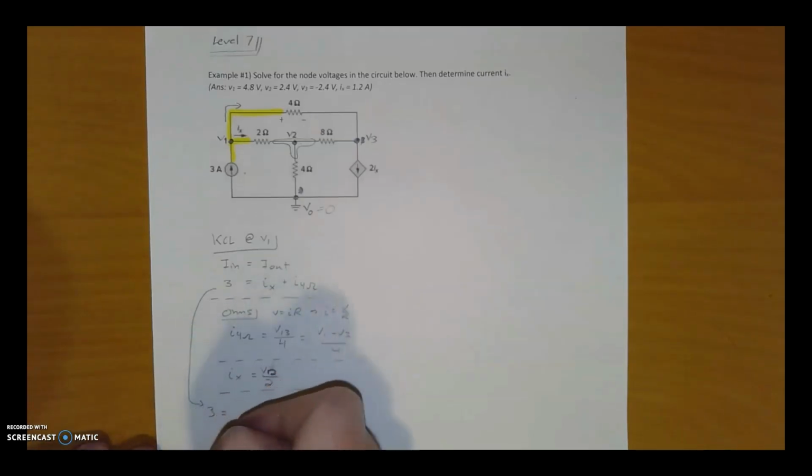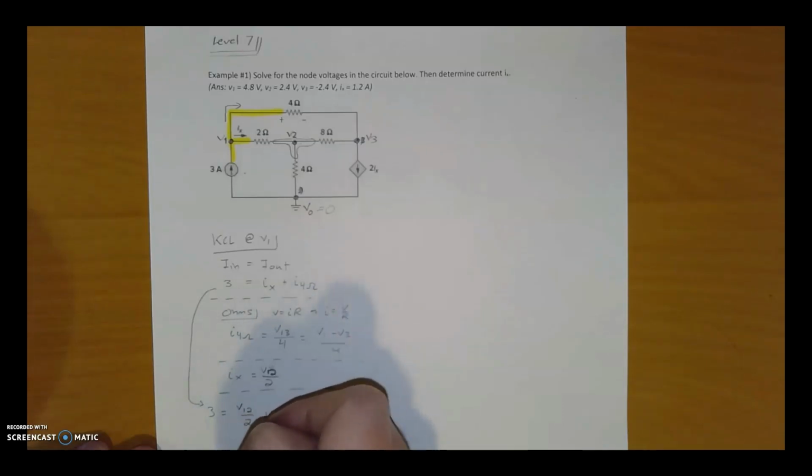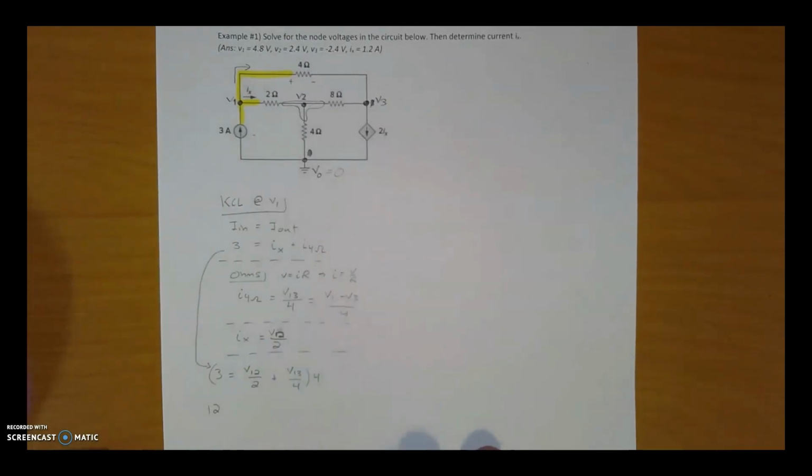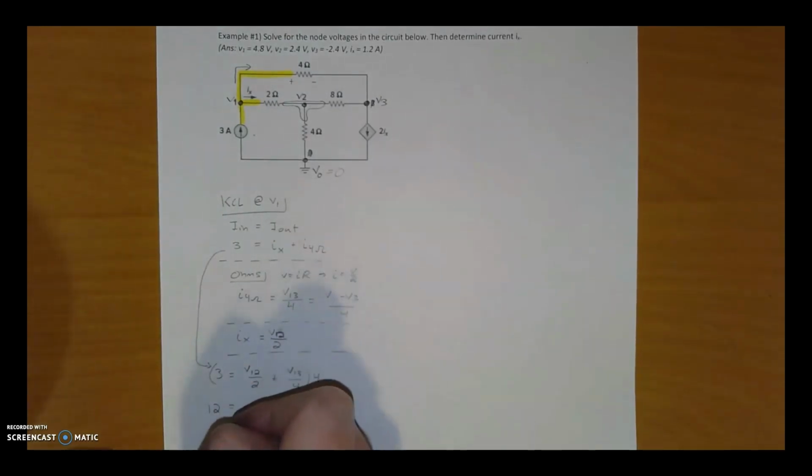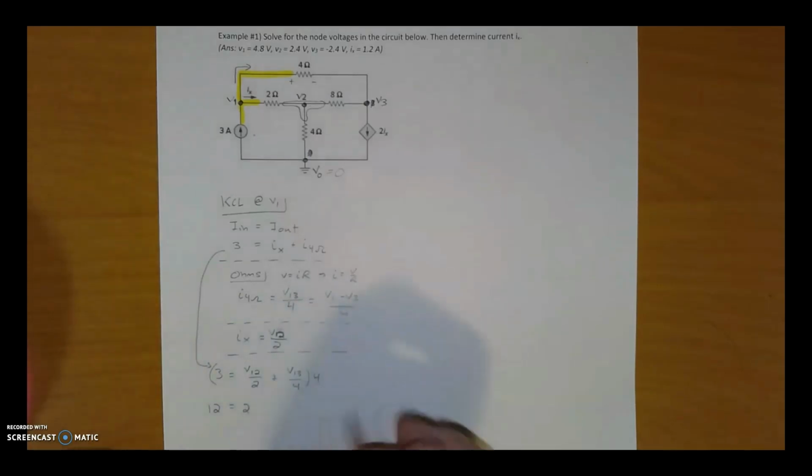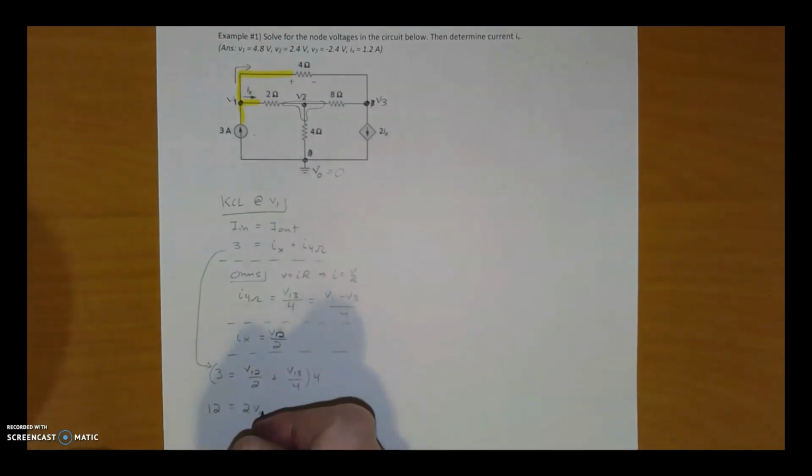So we'll sub both of those in to our equation here. So we'll have 3 equal to V1,2 over 2 plus, and I'm just going to go back to V1,3 over 4. And then what you want to do with this is we don't want to have these denominators down here. So our common denominator, our largest one here, is a 4. So we'll multiply everything by 4 to make that go away. So we'll end up with a 12. Let me scoop this up for you. You end up with a 12 on this side, and then a 4 over 2, so you have 2. And this is when I would generally expand this, so I'll just call it V1,2 for now. And this is V1,3.